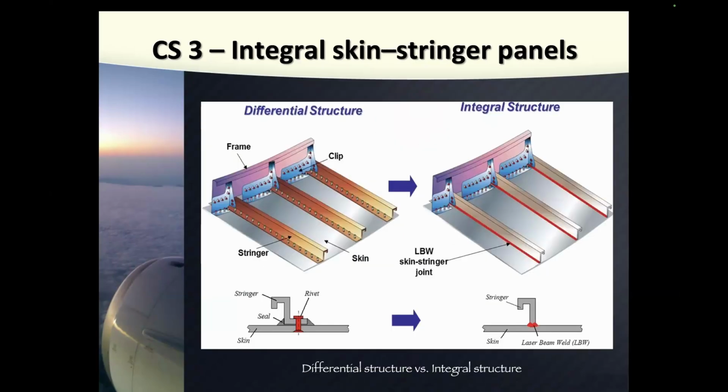Okay, so it's this thing here. There is a plate with some thickness. In this case, I think the thickness was 2.6 millimeters. And these longitudinal elements, you can see them, are called stringers in aircraft design. They carry load along their horizontal axis, okay?